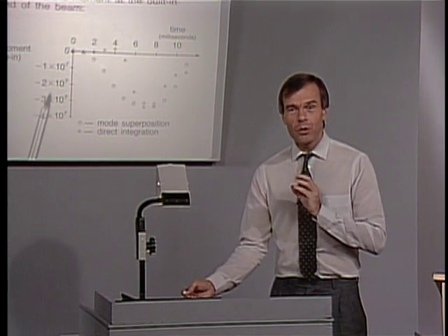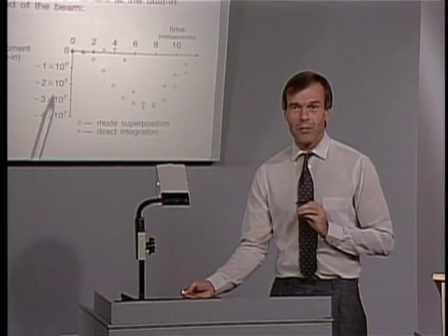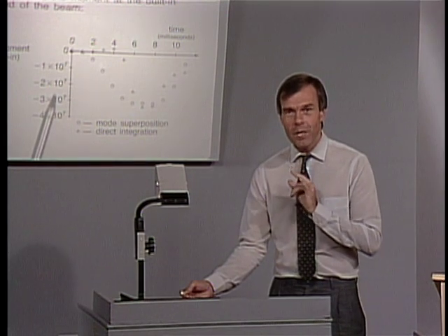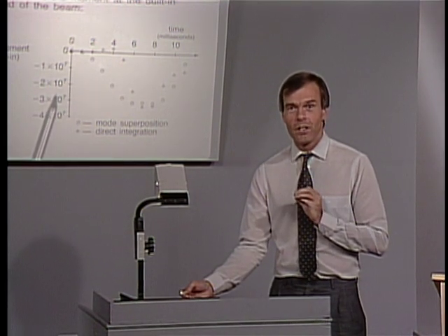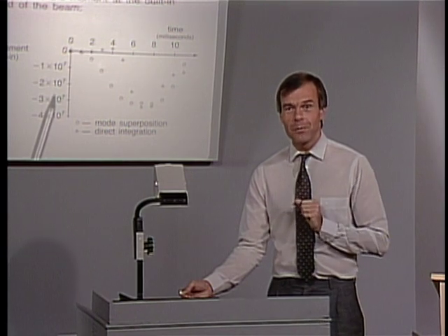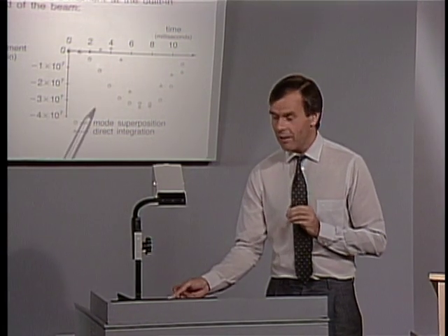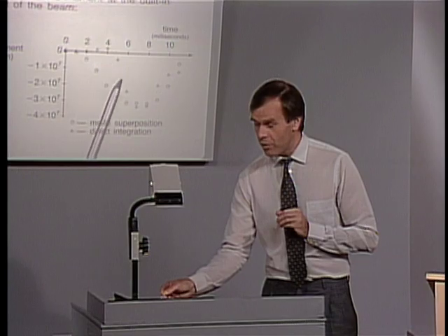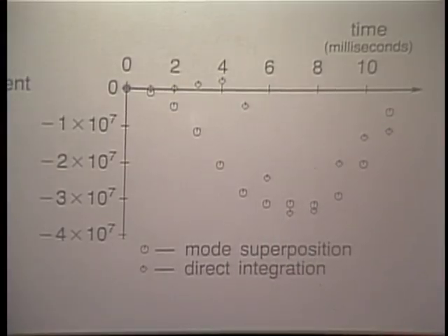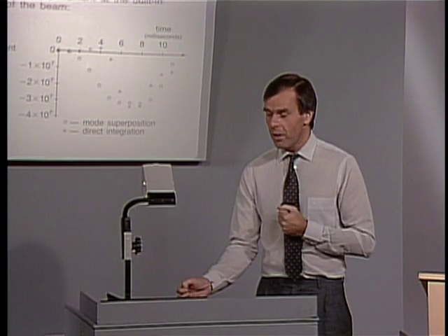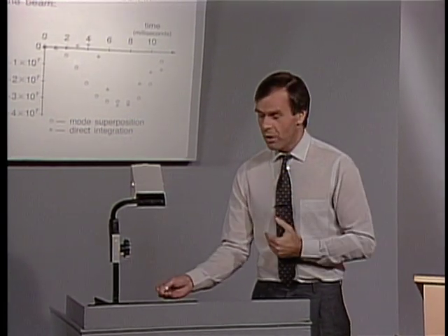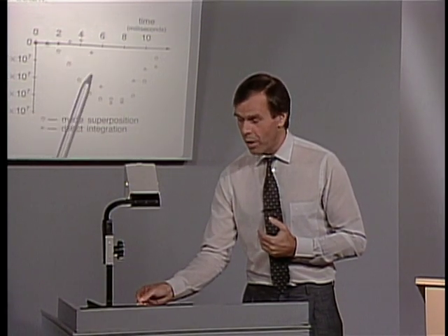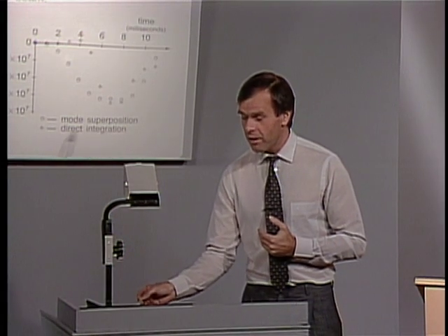So even with this initial stiffness matrix that you have used to calculate the mode shapes, if you use all the modes, as many modes as there are degrees of freedom, in this mode superposition solution, you would get the same response prediction as we are seeing here with the direct integration solution. And that means we can be quite assured that as we increase the number of modes in the mode superposition solution, we will get closer and closer to this complex response that is predicted using the direct integration solution.